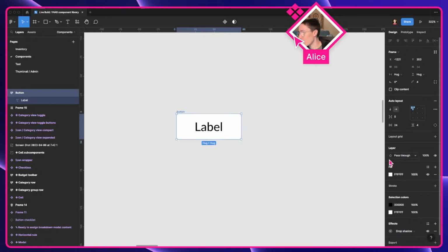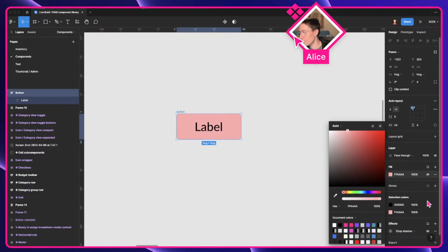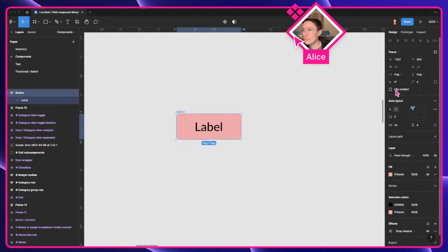The other requirement, I think this is still the case, this is my understanding, so put that fill back on, is that clip contents also needs to be turned on. If it's turned off, you can see here we have the shadow applied, but we can't see it. As soon as I turn clip contents on, it returns. So those are two requirements, which is another kind of tough constraint.